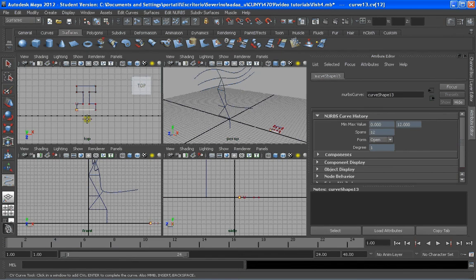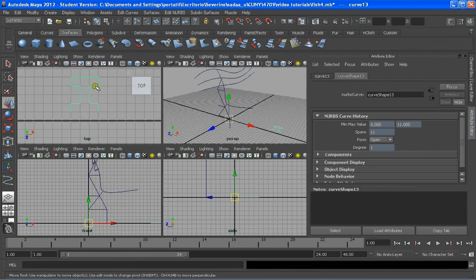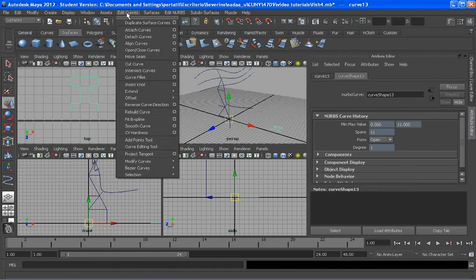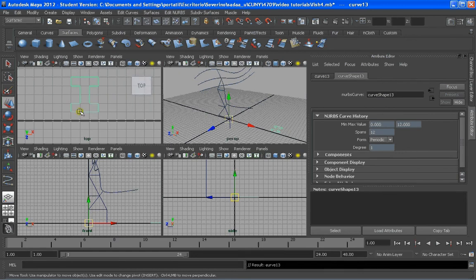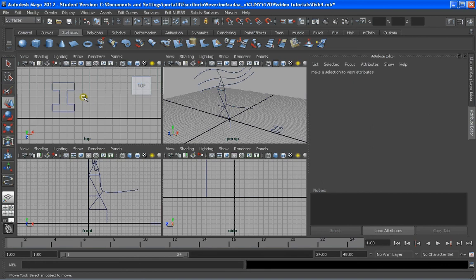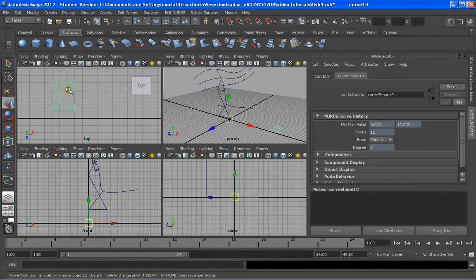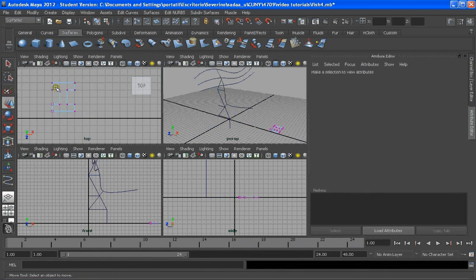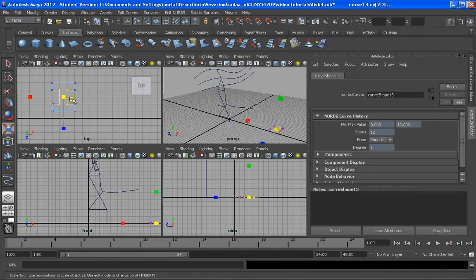Here. Oh, the last one I wouldn't draw. I would just press enter before finishing, because we can select the curve, go to edit curves and open close, so we make sure that it's closed. Another thing we can do is select the line, right click, control vertex, select this one for example, and make them bigger in this direction. Select all these ones, make them bigger.